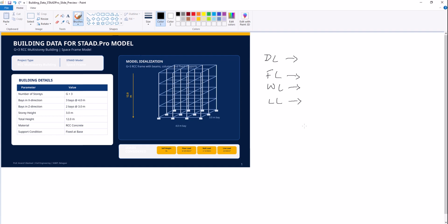As we all know, the wall thickness is 230 mm. What goes into the calculation is wall thickness and wall height, or we can say floor to floor height, which is 3 meters we have taken, and later the unit weight of brick, we can say.